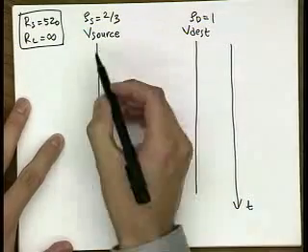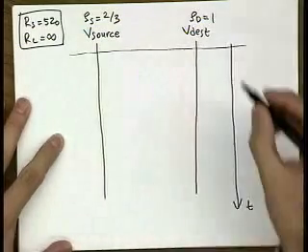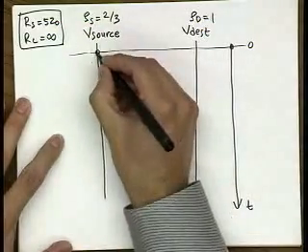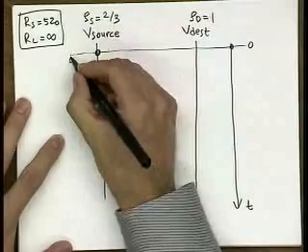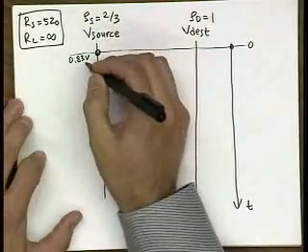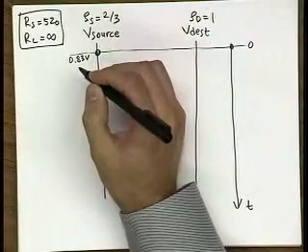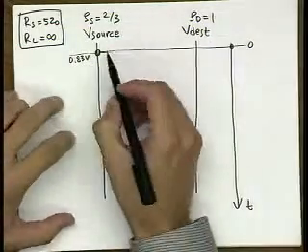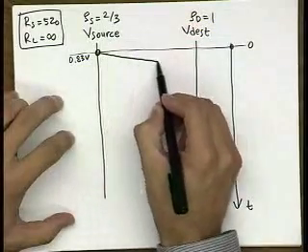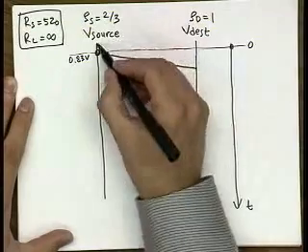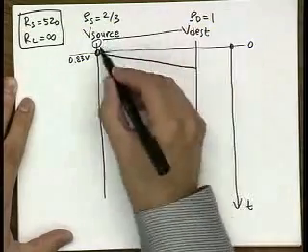So let this roll over in time. Let's start from 0. So the initial value that we had over here is 0.83 volts. So that was basically purely determined by that voltage divider when we apply the step input. Now, this signal then travels, gets injected into the transmission line. So let's say this was a transmission line over here.